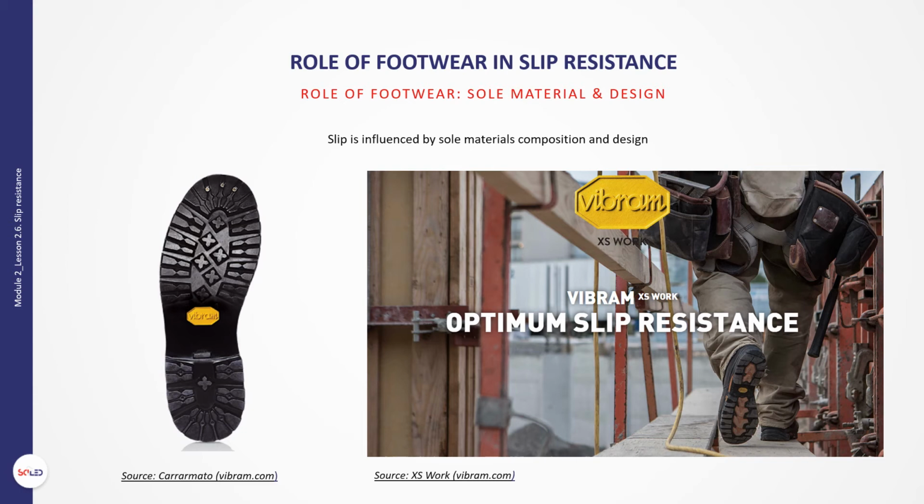For example, the circle shape is recommended because the flat edges of outsoles with hexagons, triangles, or square shapes can sometimes create a wall that prevents liquid from moving away from the shoe sole. In terms of shape size, the smaller scale is better, within 3 to 20 mm. Outsole hardness. The softer the outsole is, the better slip resistance performance could be expected. The leading edge of the cleat of the outsole pattern shall not be rounded but as flat as possible.